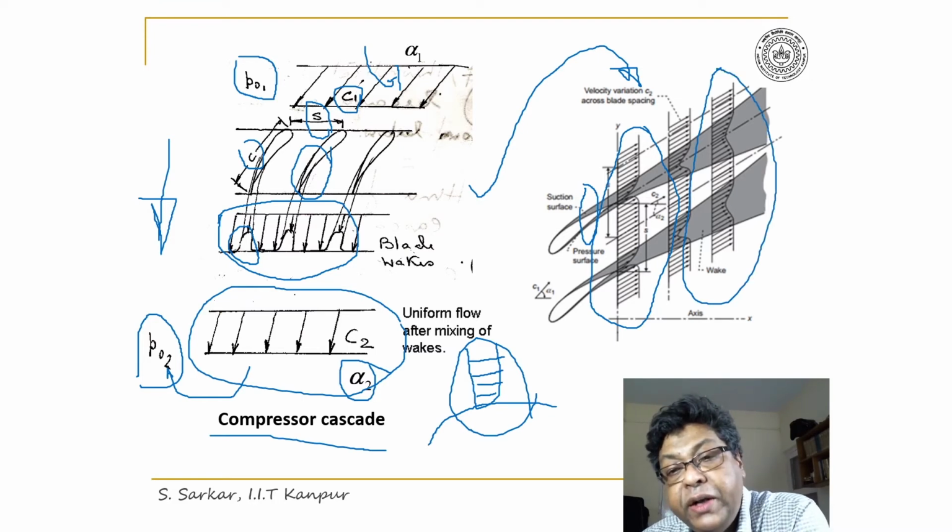The shaded region behind the blade illustrates the channel of wake, where the viscous effect is predominant due to the non-uniform velocity gradient. Thus, this figure illustrates the boundary layer formation and the channel and mixing of wakes behind the blade.